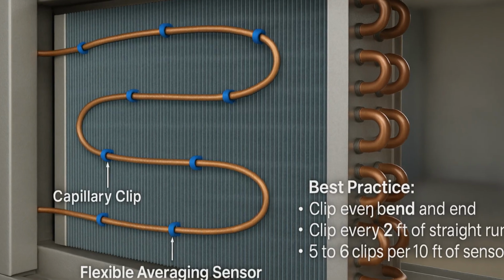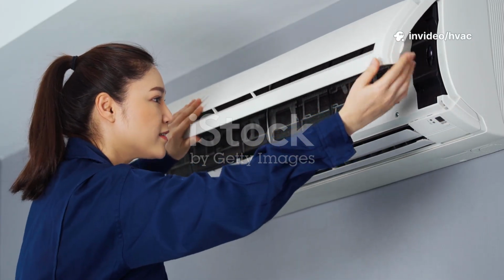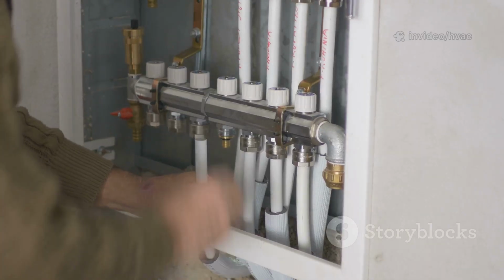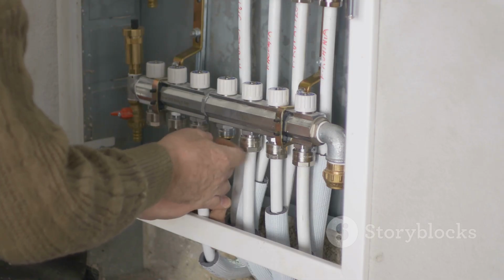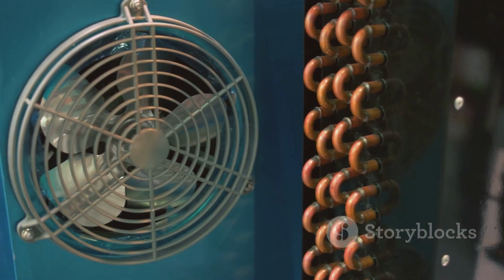Capillary clips are essential for a solid installation. Use 2 clips for the first foot, then 1 per foot after that. For a 20-foot sensor, that's 21 clips. Space them about a foot apart and add extra at bends in your serpentine pattern. Clips prevent sagging, vibration, and contact with coil fins.